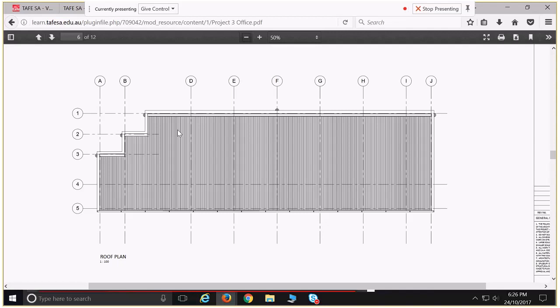So what we have to play with are rectangles that are 750mm by 1.5 metres, or 1500mm, and they can be in banks of 2, and between each bank of 2 we need that 600mm difference, but we can rotate these any way we want. So they can be vertical, in portrait view, or in landscape. They can be set out either way.